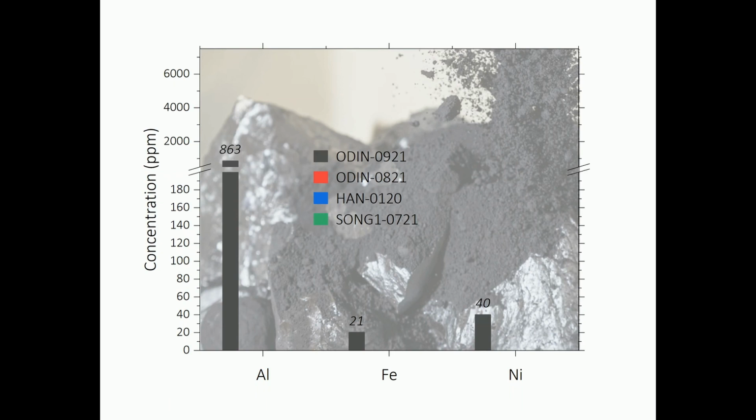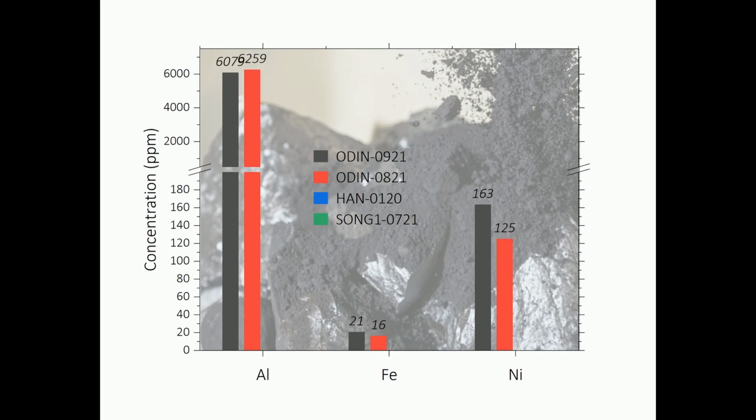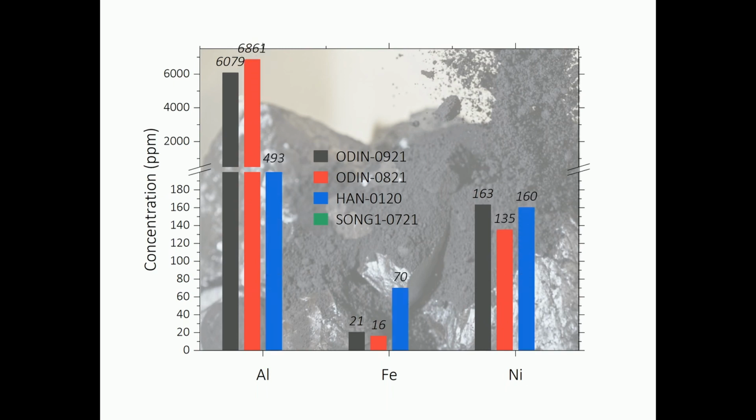Main metal impurities in silicon kerf are aluminum, iron and nickel. The main sources of metal impurities are the beam materials used in wafer sawing and the nickel-coated steel wire. The metal content in silicon kerf strongly depends on the beam material and the type of diamond wire used for wafer sawing.